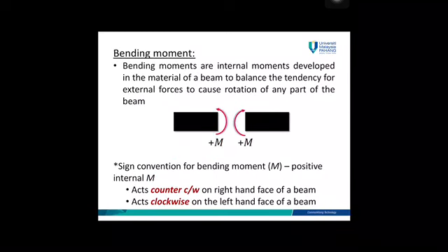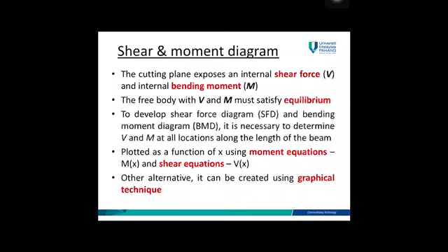As I mentioned, if you take from left, here your moment will be counterclockwise, while if you take from right, your moment will be clockwise. So this is a sign convention used by all engineers around the world. So as an engineer, you cannot change this one. This is the procedure on how to develop the equation and how to plot the shear force diagram.